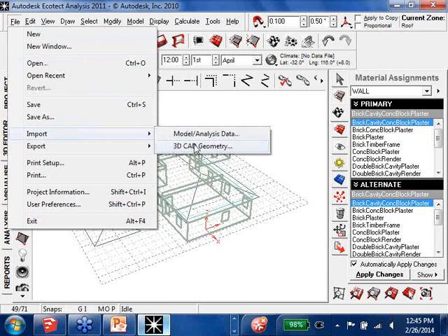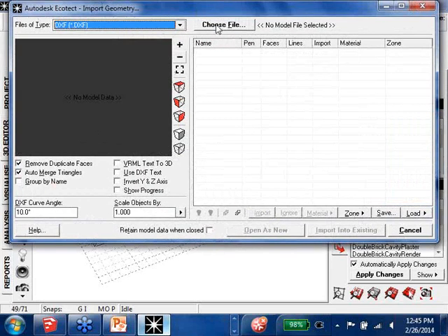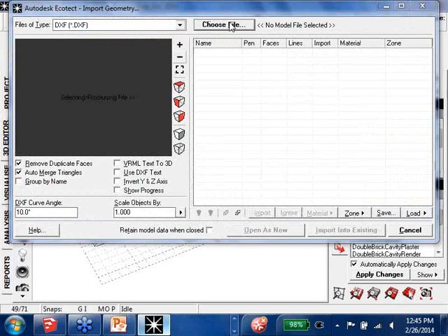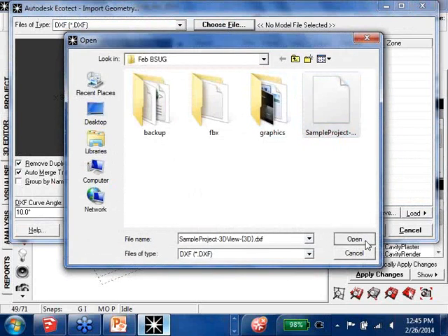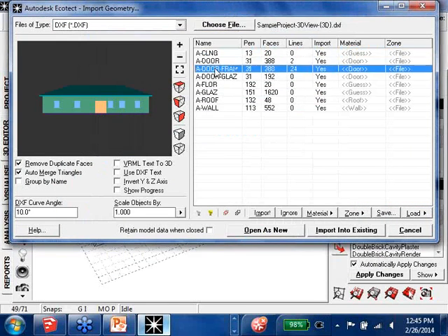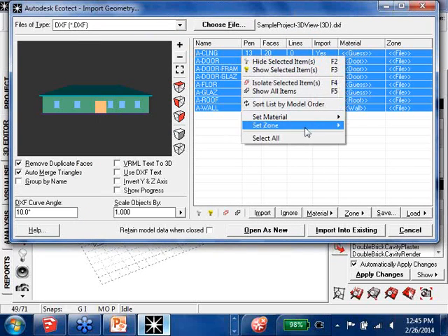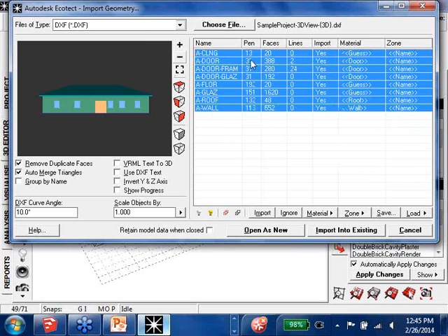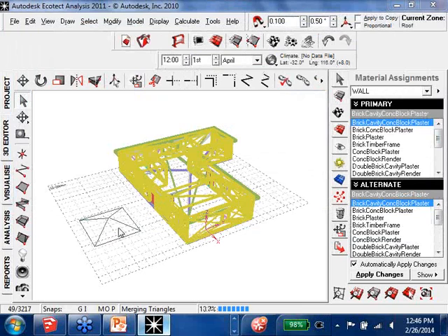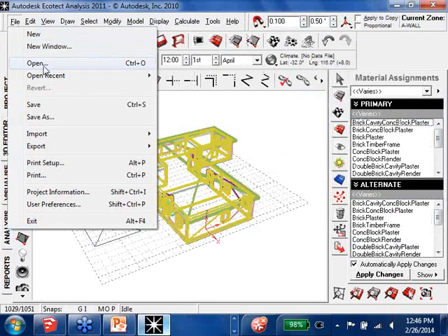Okay, and now I kind of like to show the difference. So DXF, again, is full geometry. And you can see how already the layers are set up in floor, glazing, doors, ceiling. So that makes it a lot easier to zone. You just can zone by the item name, which is this right here. And don't forget to set the scale for whatever you export it as. Oh, no. Sorry. imported that into the system.